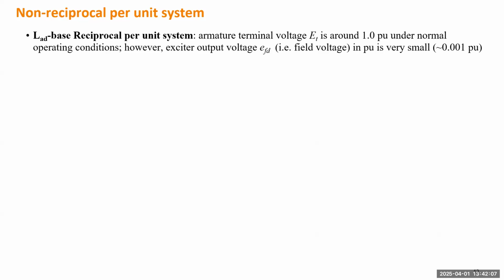Okay, so next we need to explain one thing. We left this question from the generator modeling session. If you remember, there was one very busy slide where we started from a flux linkage equation and voltage equation, and gradually derived a set of differential equations using only the time constants and Ic single prime, Ic double prime.